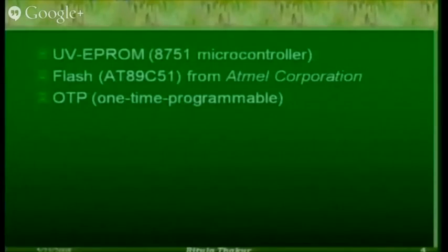So you require an ADC. Now in some controllers, this ADC is not available on chip, but there are some controllers available in the market today which have an on-chip A to D converter as well. So such features also distinguish one controller from another.